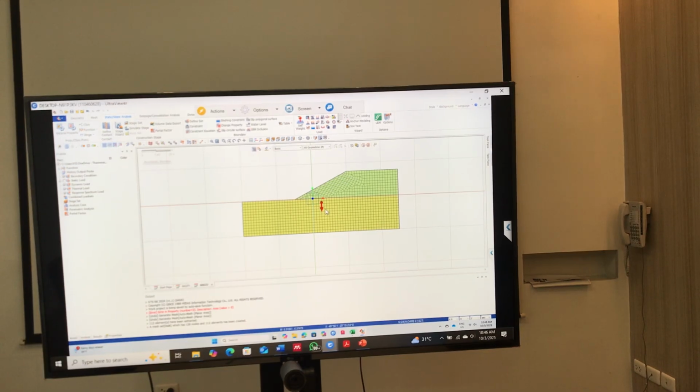So you're adding both of them. Yeah, the self weight is already there. Okay. Now, assuming that this is the soil, you are applying some force on it. Does it mean that you have taken the weight which was in it? So that's why you need to keep the self weight inside. Okay, so this is the first boundary condition, the loading.